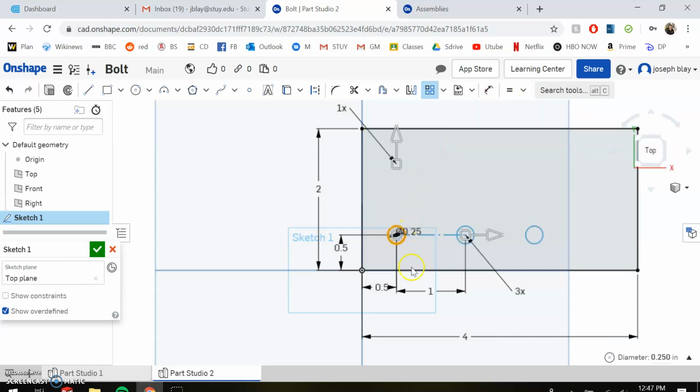I'm going to click on the circle. I'm going to set the distance apart. I'm going to leave it alone at 1 inch actually, because that's kind of nice for this. Number of instances horizontally, I'm going to make 4. So it just creates that. And I actually want to make it go up as well.